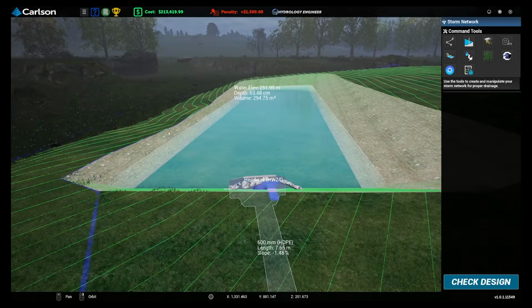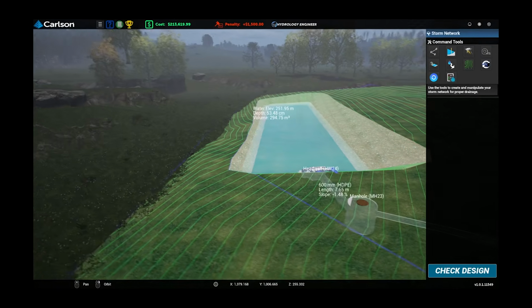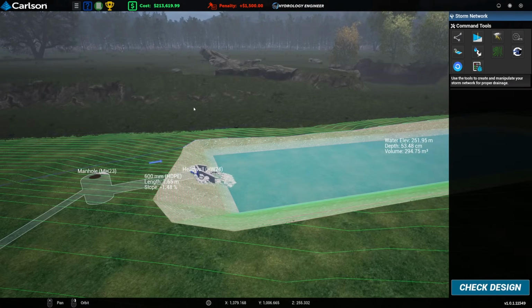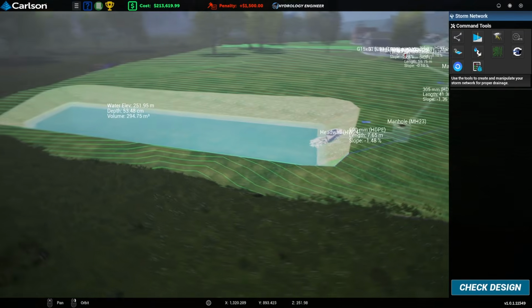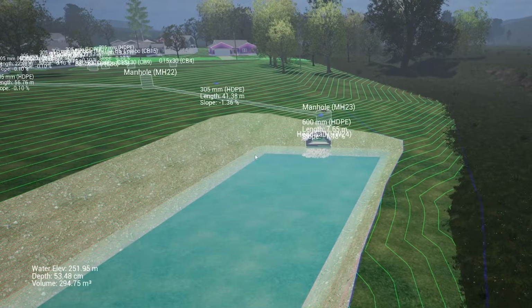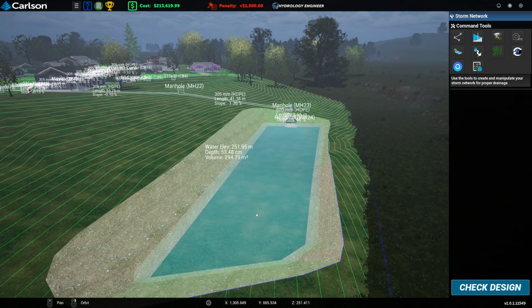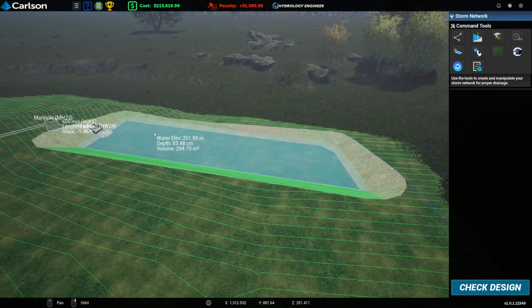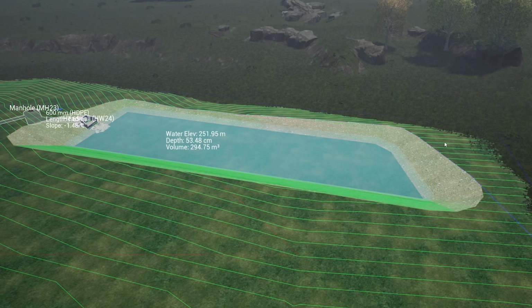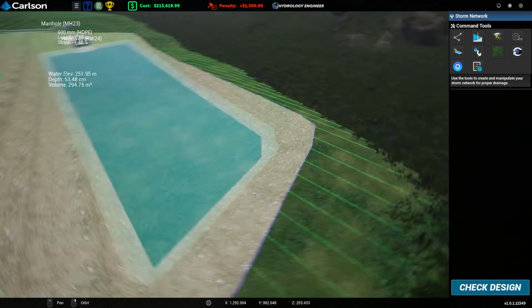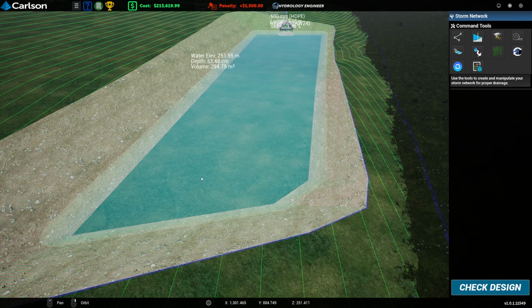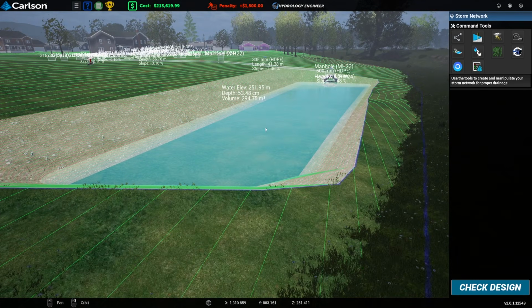And obviously if you start eroding your pond, you're going to cause issues. Not only will there be sediment and everything in the pond, you could flood somewhere downstream, etc. So generally just a good practice thing to do. It gives you the longest length as well. And then should this just be a storage pond, we have an outlet from it, we'd put the outlet down this end so that all the water has to travel along the entire length of the pond. That allows sediments to settle, it allows a bit of evaporation to happen.